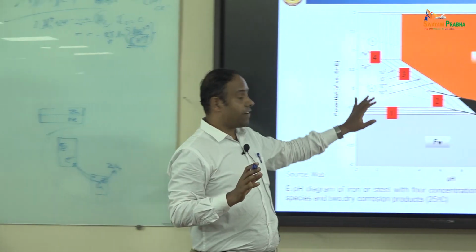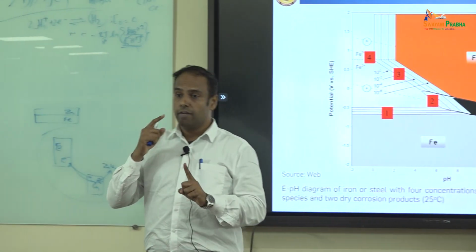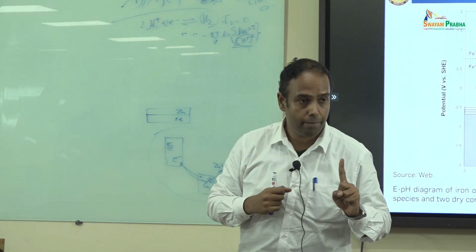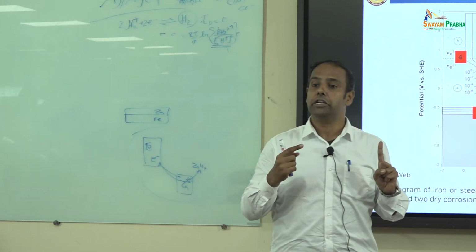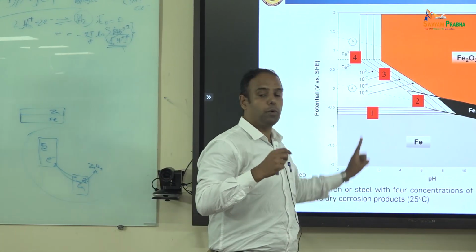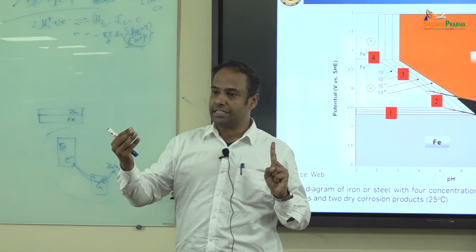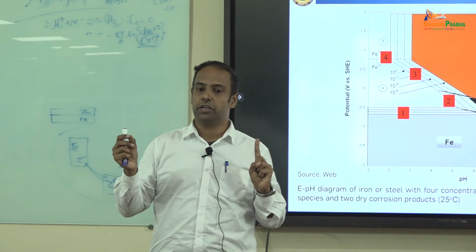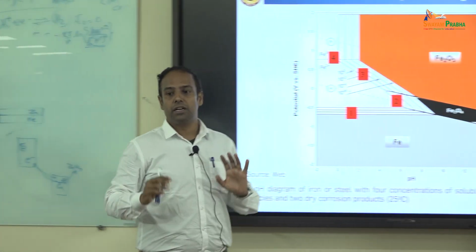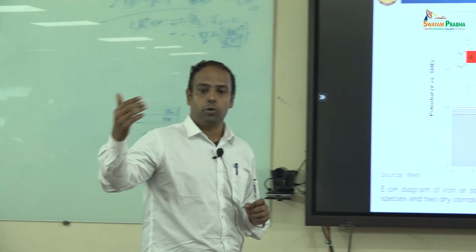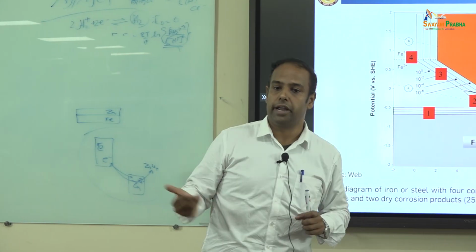Of course, there are a lot of assumptions made in the Pourbaix diagram. The first assumption is that the activity of the active elements is 1, but it need not be. If you have multiple systems, the predominant system is considered to be 1, but the activity need not be 1 for each. So that becomes a deviation, and as I did the calculation, it also depends on your delta G value, which you need to get from the chemical data.